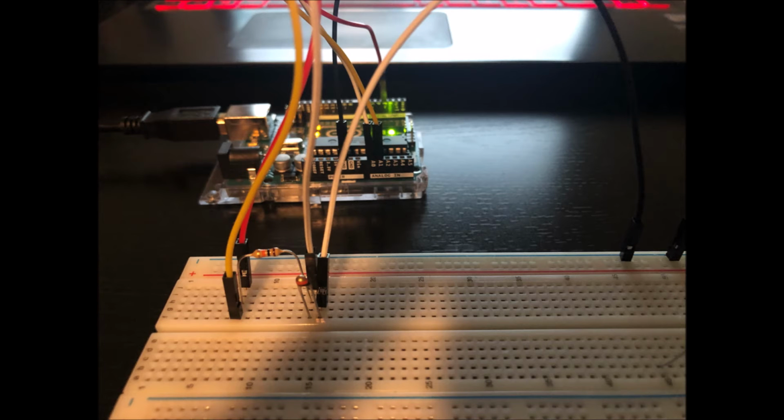Now we've replaced the capacitor in our circuit with a thermistor. The sensitivity of the output voltage is at a maximum when we use the 10,000 ohm resistor rather than the 100,000 ohm resistor. Ideally, no resistor would be the maximum, but between the two in the lab, 10,000 is what we're going to roll with. The time constant I've selected is 15 seconds, as was taken from the data section of the data sheet.